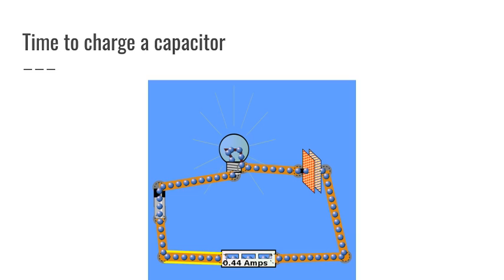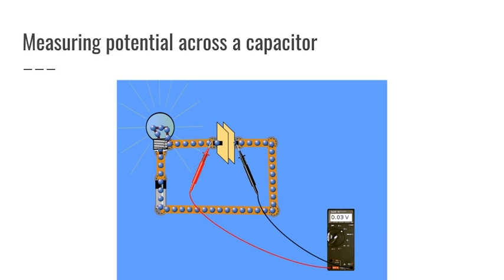Next, we replaced the 10 ohm bulb with another which had 20 ohms of resistance. This time it took 18.15 seconds for the capacitor to charge and the same amount of time for it to discharge. The last experiment we performed was to determine the constant of an RC circuit which contained a 9 volt battery, a 200 millifarad capacitor and a 30 ohm light bulb.